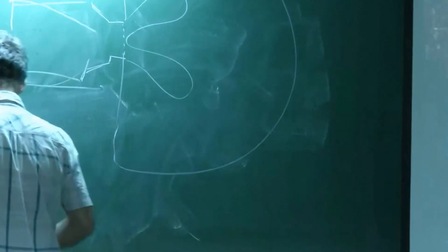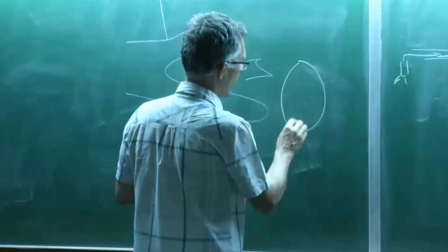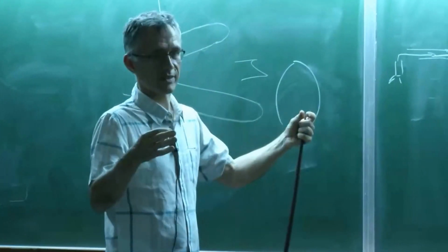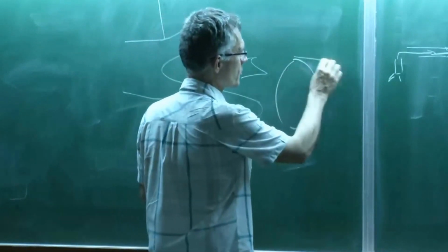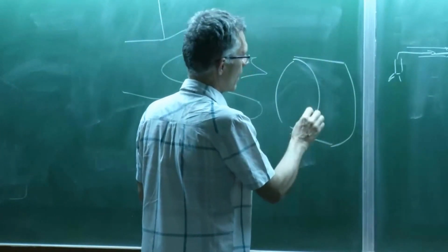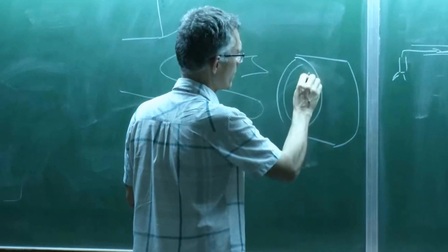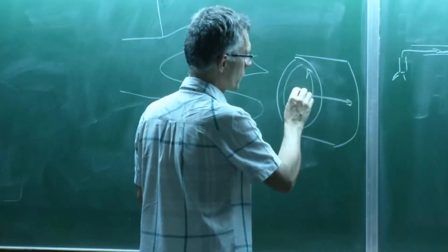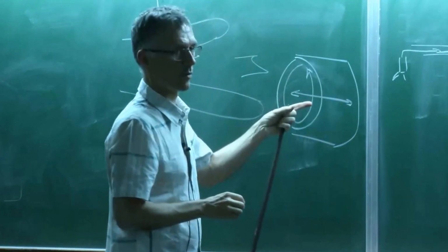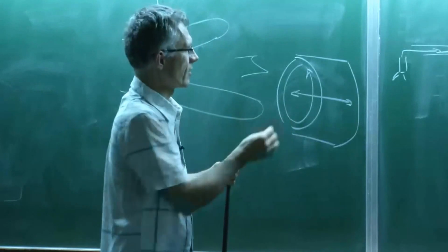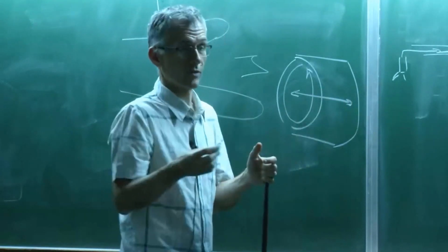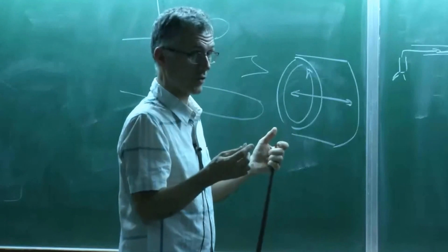All these modes, all the modes are controlled by length, okay? So if you have an engine which is compact, this distance here is of the same order as this one. So the azimuthal modes are at the same frequency as the longitudinal modes. And that's what happens in most cases in gas turbines.